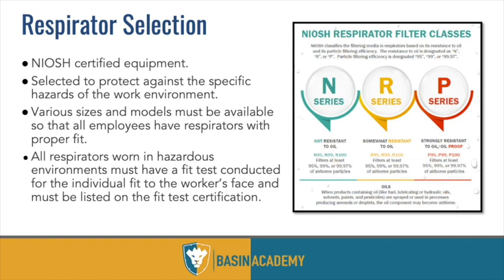NIOSH has some different recommendations for selecting the proper respirator. And respirators, when they're made, have to follow ANSI standards, just like safety glasses and boots and FR. They have to follow a certain standard. Within that standard, though, depending on the contaminants you're working around, that will change what type of respirator you use, not to mention the type of cartridge that you use.